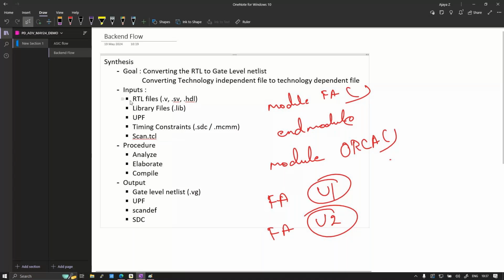So now, .lib, should I extract it? Those have the gate level information only, right? That is already extracted by the other team. I'm just using it, so no need to re-extract it again. It's a waste of time, waste of memory. As that is a global file, I can use it for different stages.